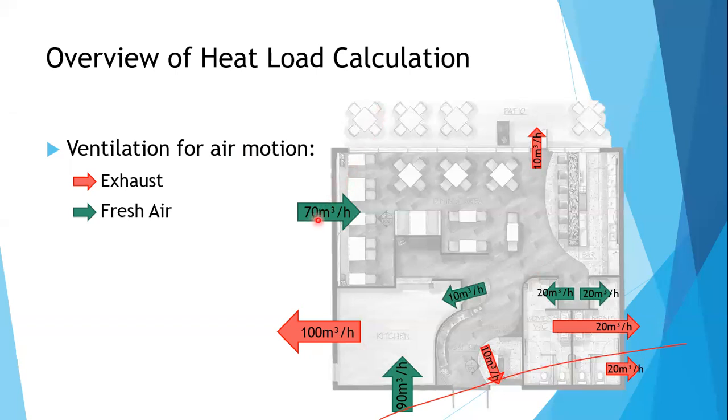So using positively pressurized and negatively pressurized spaces, using the difference in exhaust air and fresh air, we create the positively and negatively pressurized spaces. We are able to control and predict where the air will go, or what will be the motion of air inside the space. Okay. Just take note, when you exhaust out, the fresh air has a minimum,